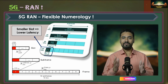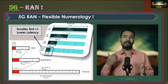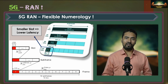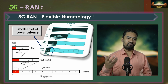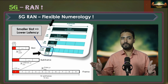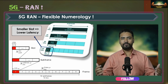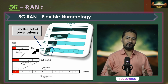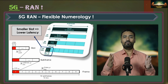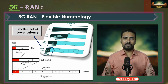Like LTE, 5G NR also has a 10 millisecond frame structure, but now it has added more flexibility in the subcarrier spacing. That means unlike LTE, 5G NR supports a range of subcarrier spacing from 15 kHz to 240 kHz. So that provides more adaptability for different scenarios. Although this picture here only shows up to 120 kHz, please remember that NR can support up to 240 kHz subcarrier spacing for even more flexibility.